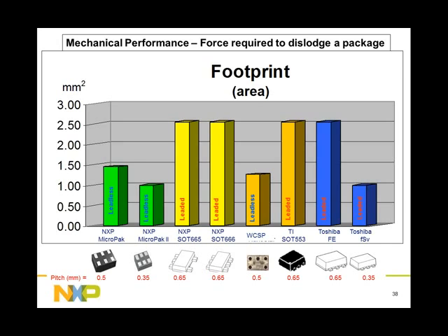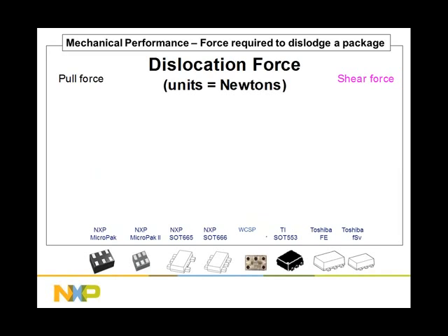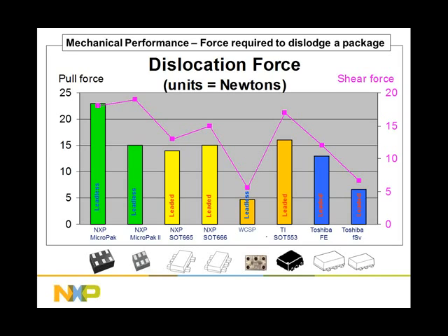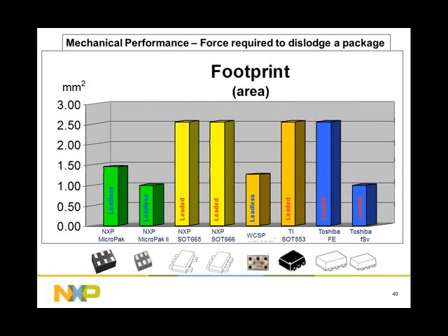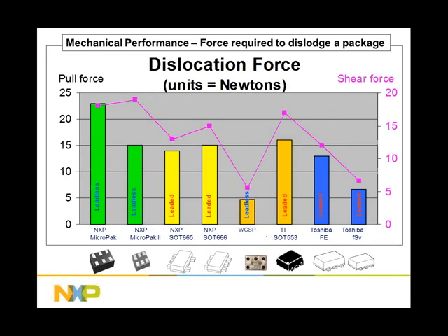We then looked at what the forces were required to pull the part off the PCB, or the shear force to slide the part off the PCB. And this force is measured in newtons. And we were surprised to see that the leaded packages required more force to dislodge them than the leadless packages, even though the leaded packages were larger physically than the leadless packages.